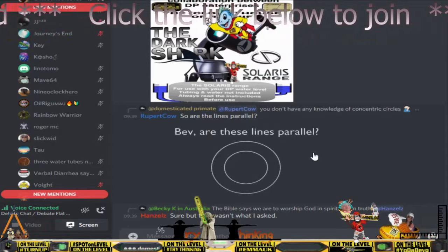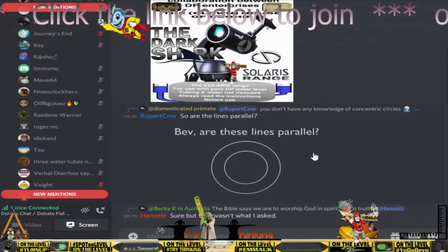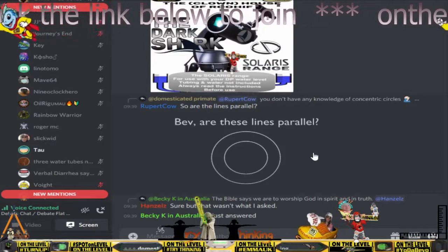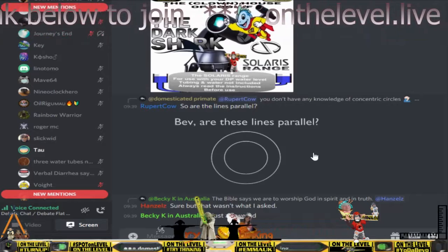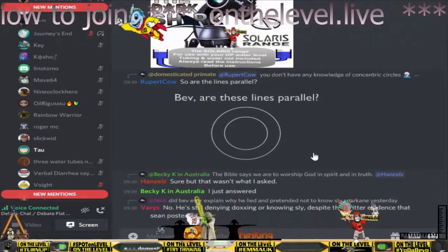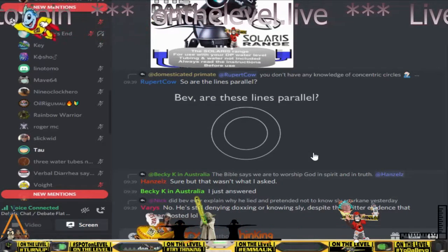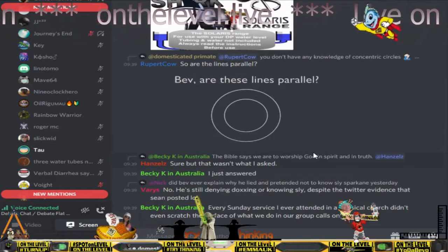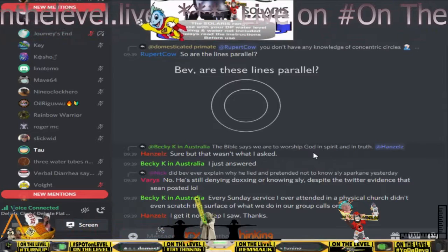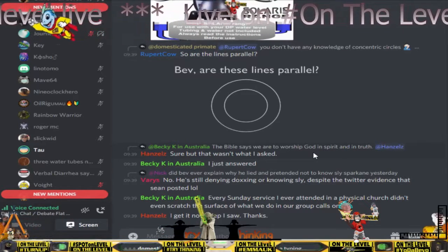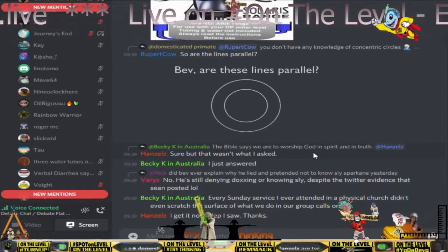Rupert, no, they're concentric circles. They share a similar centre. Two equal lengths of clear pipe. Stick one in the water to the bottom of the bed of the level. Go to the other end of the level. Stick the clear pipe in that down to the riverbed, yeah? And then make a mark on each one with a pen. Then measure the length of the pipe and there's your drop. Off you go. On a river, because it's flowing.